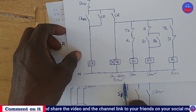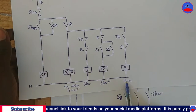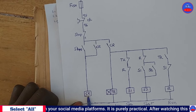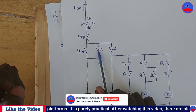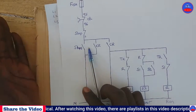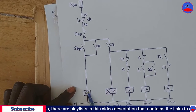All right, okay. So now I said this is our star contactor, start contactor, and then run contactor. When the start button is pressed, the control relay will energize. This contact will close to serve as a holding-on contact, so that when our start button is released, this side will close to maintain this one. This side will also close because they are all open contacts on this contactor or relay.